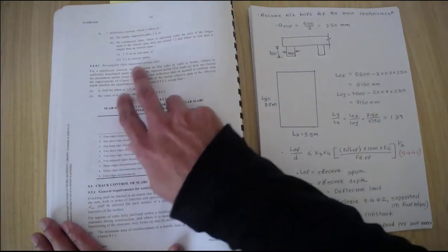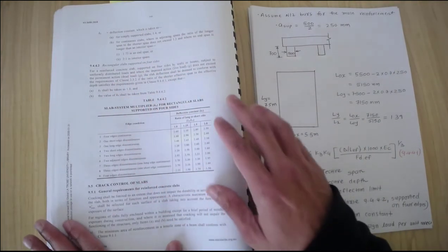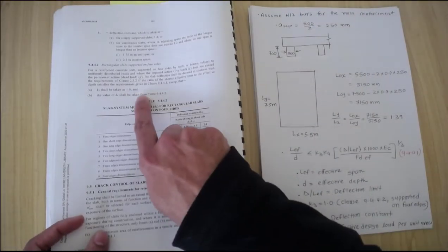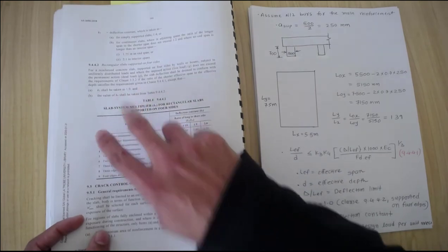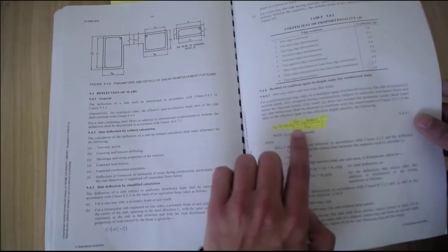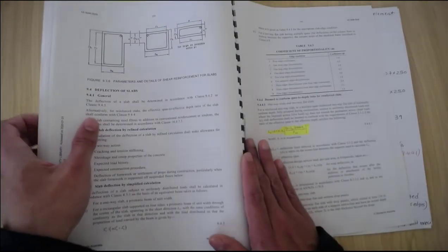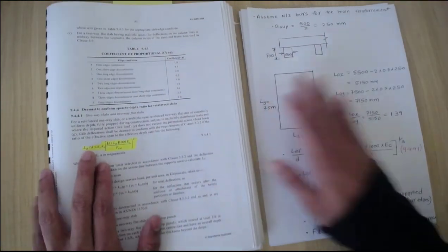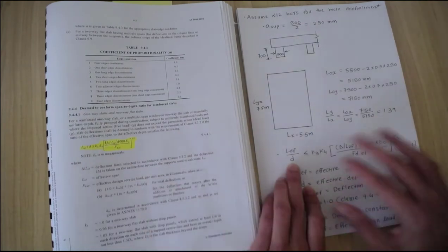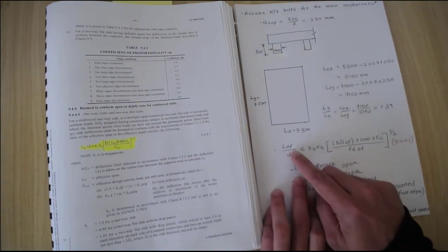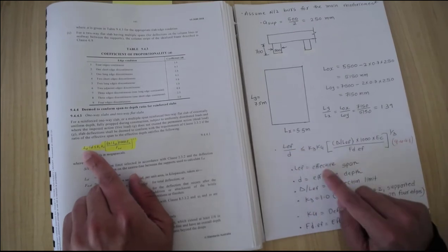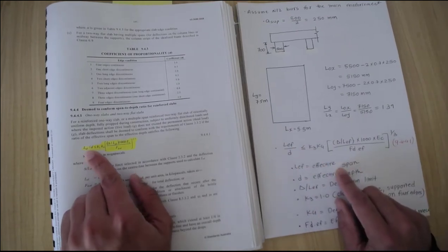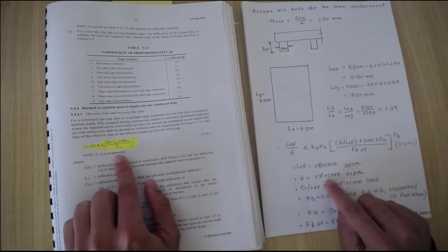Now if you read this one, they are basically the same equations as over the page, but the difference is K3 and K4 that we are going to extract from here. So we are going to work on these equations, but the only difference for a rectangular two-way slab where four edges are supported is you will have these equations. Now I copy these equations. Let me identify each parameter. LEF on the left side here is called the effective span, and in the last video we talked about what the effective span is. This small d is the effective depth.